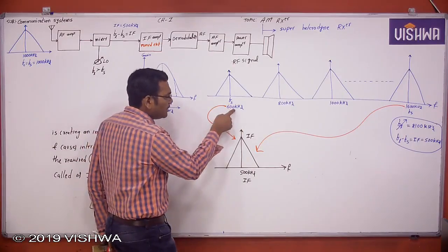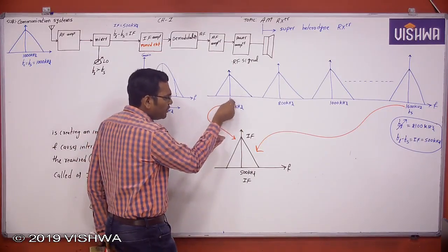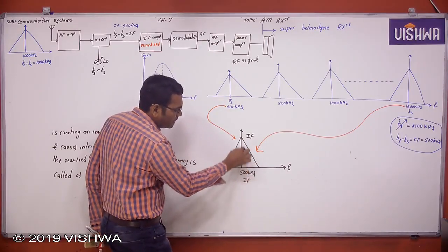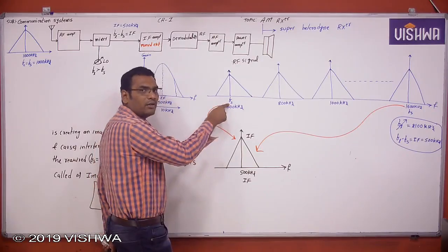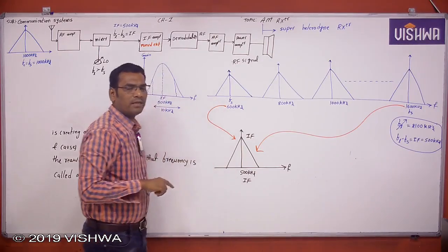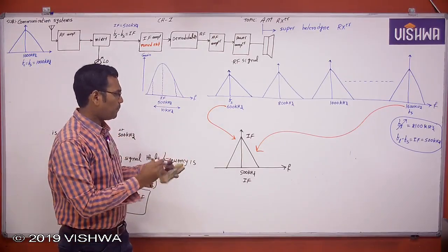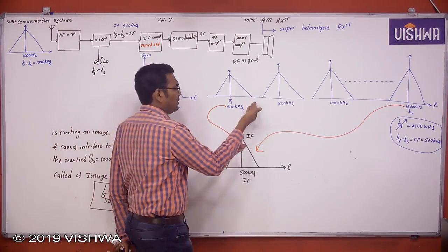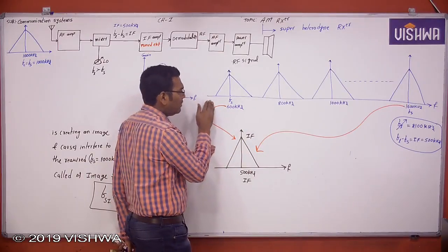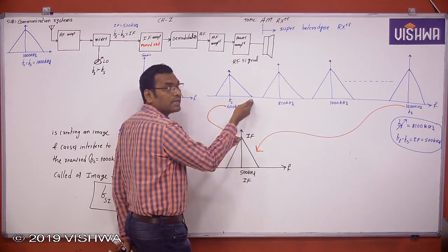This is 600 kilohertz with a bandwidth of 10 kilohertz. Now these are passbands, or not? Here, 600 kilohertz is the center frequency, because this is 610 and this is 590, 590 to 610.